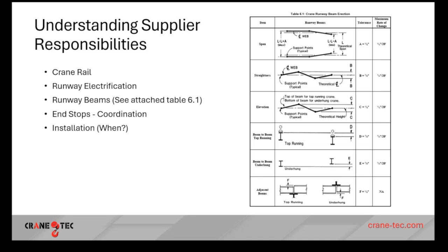We do not need a section of the roof left off, and if we do, we'll ask for it. I like to install all of my cranes in the last 20% of the project at the very end when we're working on finished floor. That's our preference. That's what we found works best for installing overhead cranes.